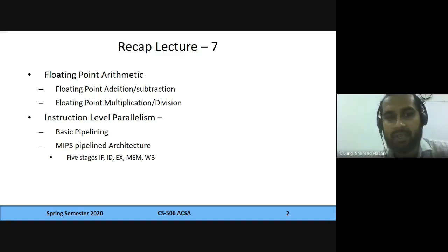And then the memory stage is the fourth stage, which is used only by two types of instructions: the load instruction and the store instruction. Now in the RISC processor, what happens is that you simplify the design. So you only allow operations between registers.